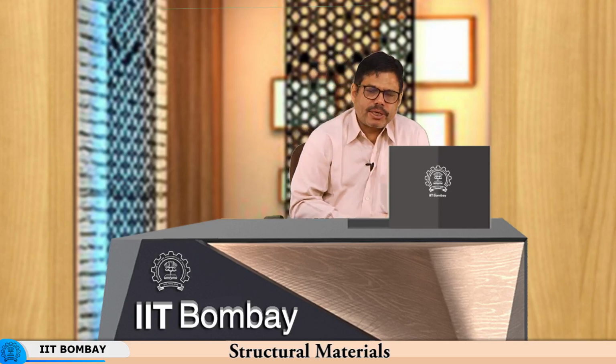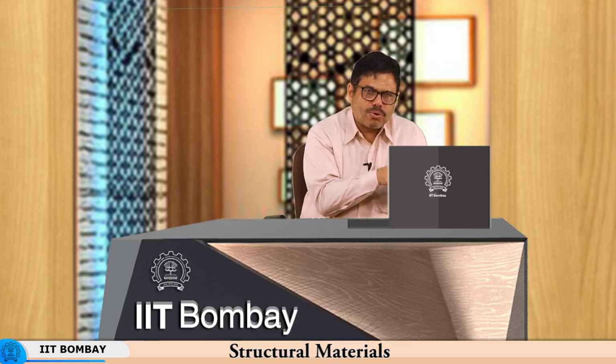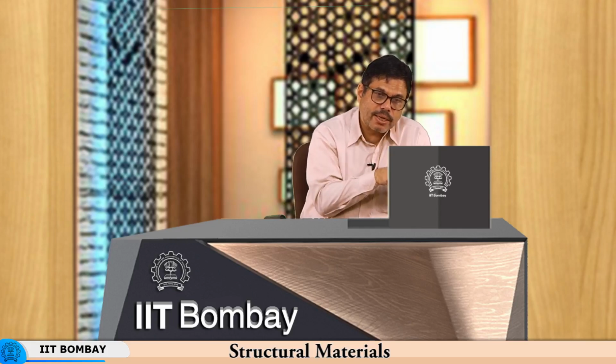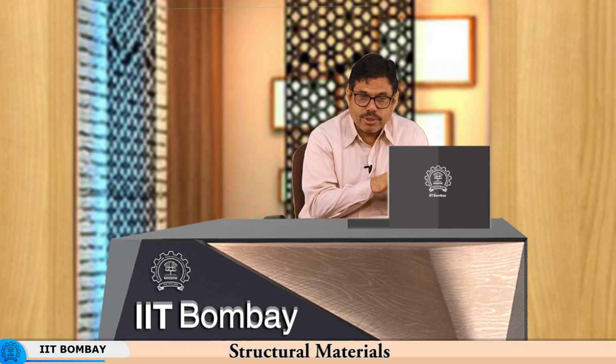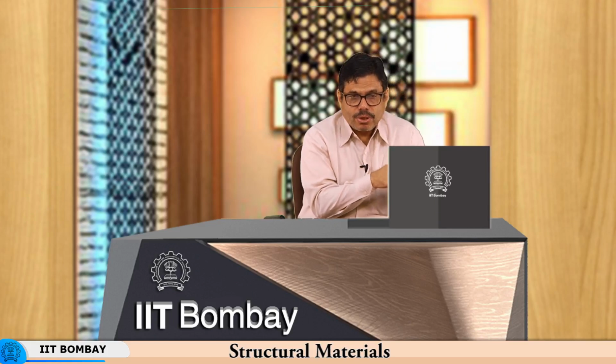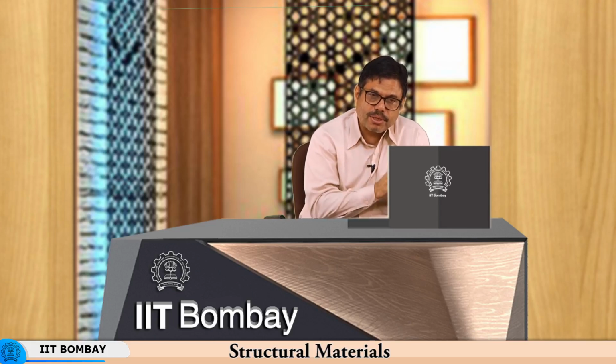Similarly, you have tools, let us say forging tools or forming tools, where the tool comes into contact with the workpiece and the contact gets released. Again it comes into contact, it is loaded. So, the tool surface continues to get loaded and unloaded cyclically, and the number of cycles the tool can see can be as high as a few hundred cycles per minute. So, the number of cycles can be as large as that, or they can be as long as in the case of a boiler, where the boiler can go for a number of weeks, a number of months before it is shut down